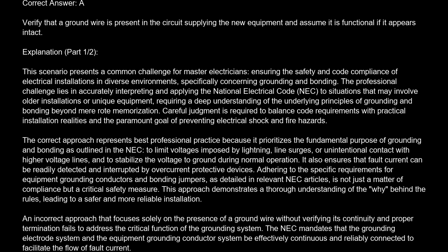The correct approach represents best professional practice because it prioritizes the fundamental purpose of grounding and bonding as outlined in the NEC, to limit voltages imposed by lightning, line surges, or unintentional contact with higher voltage lines, and to stabilize the voltage to ground during normal operation. It also ensures that fault current can be readily detected and interrupted by overcurrent protective devices.